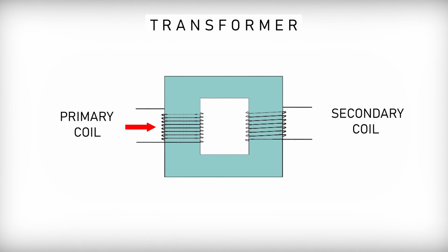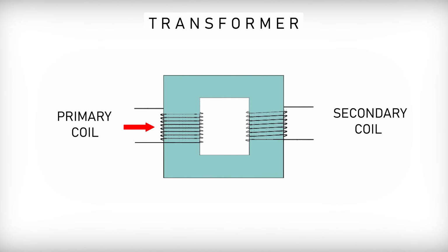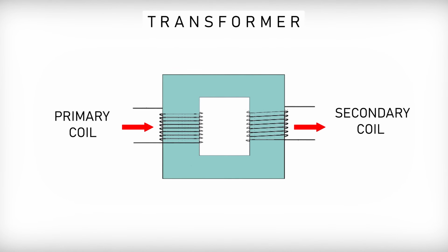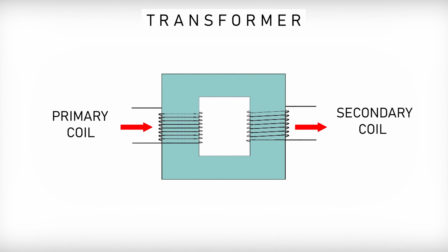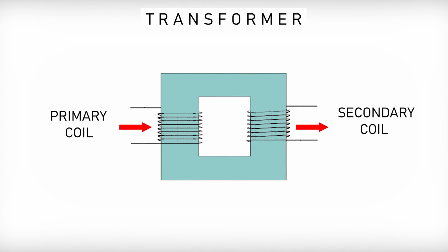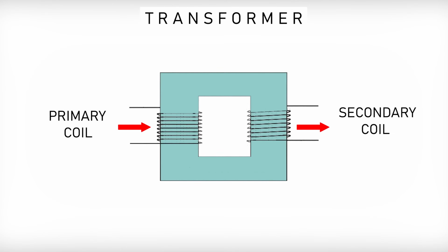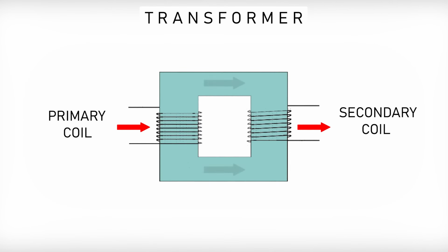The input voltage is fed to the primary winding, and the output voltage is picked up from the secondary winding. When AC voltage is applied to the primary, the energy contained in electric current is converted into magnetism, which, passing through the magnetic core, then gets converted back into electricity at the secondary coil. And that's basically the method that allows transfer of electric energy without electrical contact.